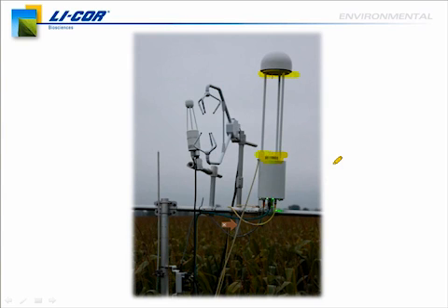I'll explain how that works, but that allows us to operate this open path instrument in real-world environments like cornfields or wetlands or Arctic areas. When the instrument senses that deposition is occurring or that the optics are getting dirty, it cleans itself, so you don't have to be on the site monitoring the instrument performance and cleaning the optics regularly. There's an air temperature thermocouple very near to the optical path.